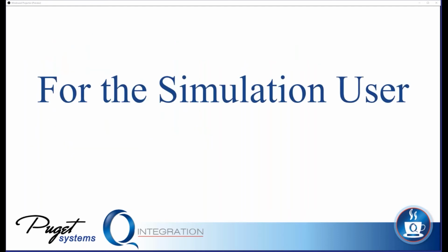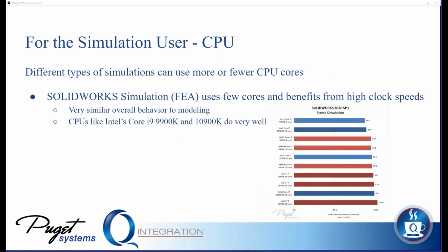And then moving on to simulation folks, there is a little bit of difference here depending on what sort of simulation stuff you're doing within SolidWorks. If you're using SolidWorks Simulation, that particular package is primarily finite element analysis, and that tends to only use a few cores but benefit from high clock speed. So very similar to what you'd have in a normal CAD workstation. The same sort of processors do very well, like the Core i9 processors from Intel. The Ryzen stuff's a little bit behind that, but not by much.